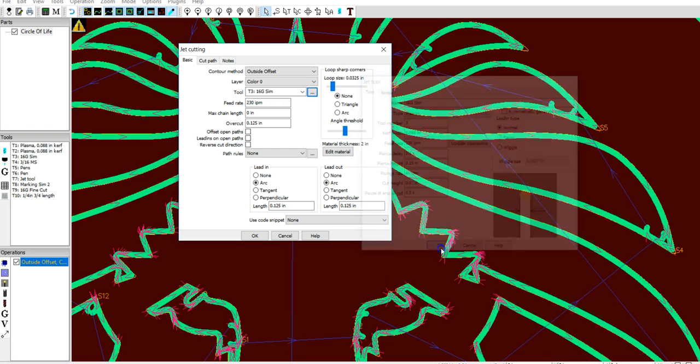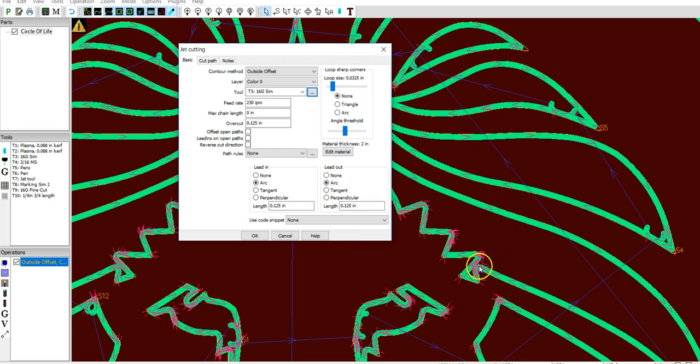So let's take a look here. We hit OK, and if you noticed, and if you didn't see it, go back and watch when I hit OK. The width of this line actually increased slightly because, of course, I'm adjusting the simulated kerf width, and so it's moving that blade slightly further into or outside of the drawing or the shape here in order to make sure that the plasma cutter doesn't overburn or cut too far into one way or another.